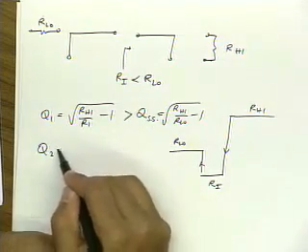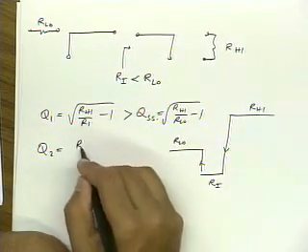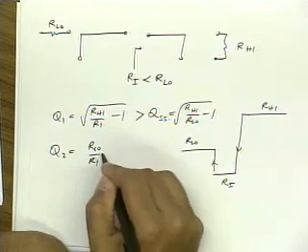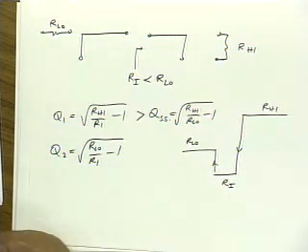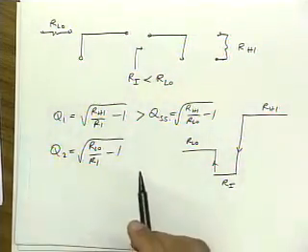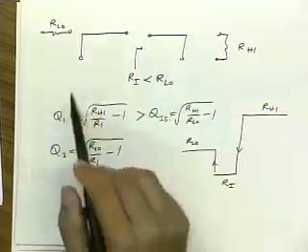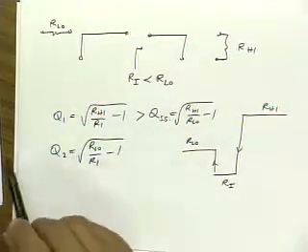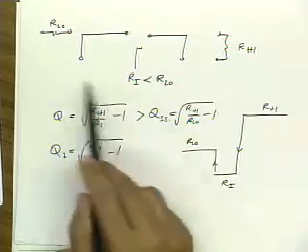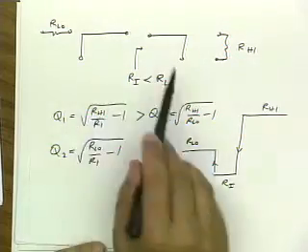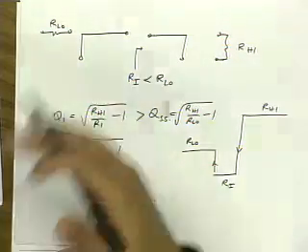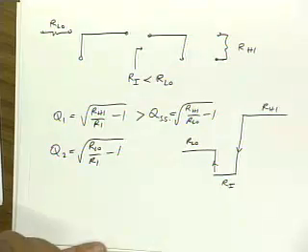And Q2 is perhaps even higher as well. So it'll turn out, and we'll show this later in the lecture, maybe next lecture, that the quality factor of this overall matching network is the average of these quality factors. So I've raised the average quality factor, so this is going to be a higher Q circuit. So it's the opposite of the previous case.